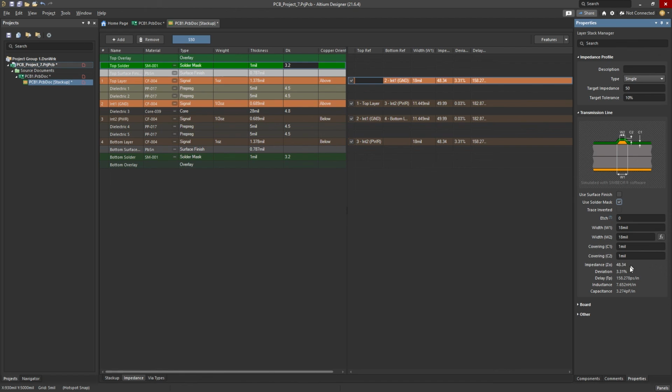And so if that's the case, and I want 50 ohm, here's my target impedance, I can ask what line width do I have to go to with the solder mask to give me 50 ohms? Well, that's easy. I know I have to use a narrower line because I want to increase the impedance, and I'll let Simbeor calculate it for me directly. What's the line width? Oh, 17 mils gives me a 50 ohm target impedance.